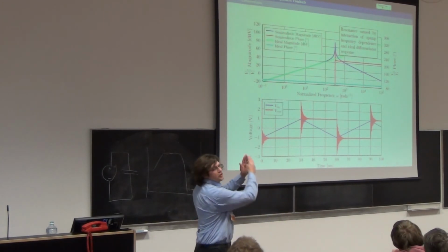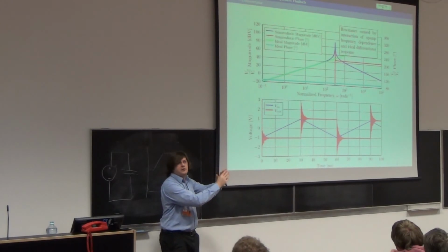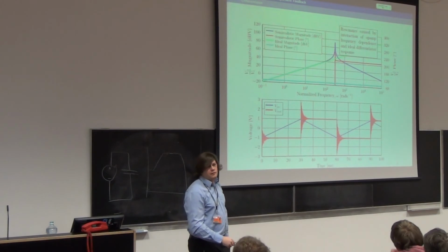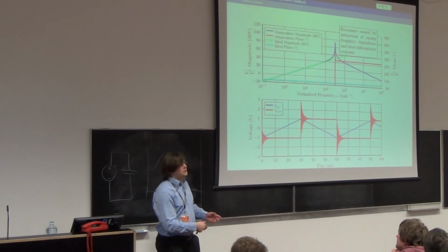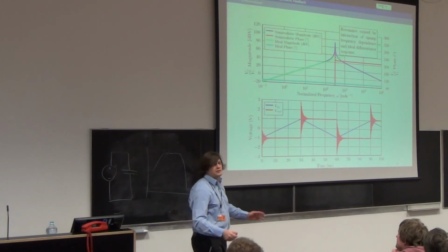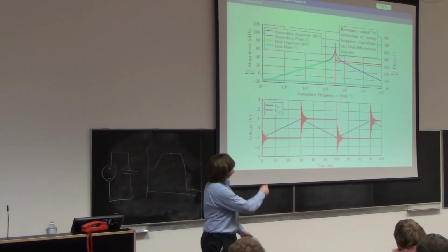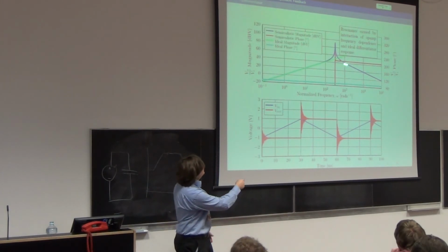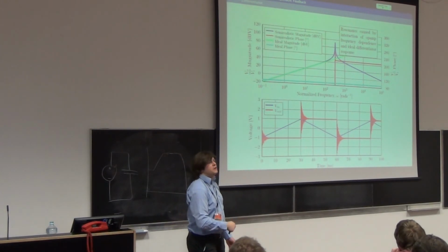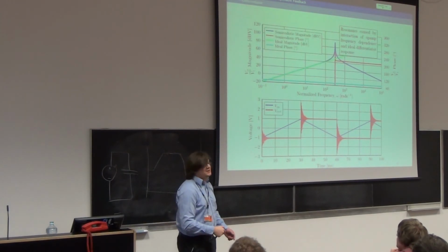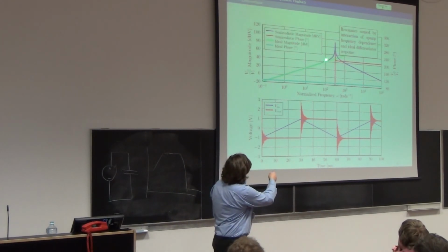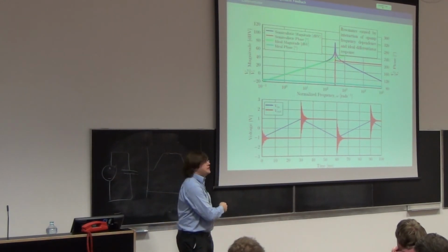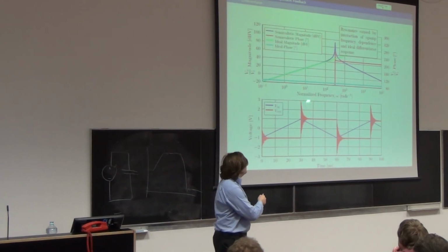If you increase the Q, it makes it sharper. Decrease the Q makes it more spread out. So you have to think about it. My comment about bandwidth and Q was separate. You can either reduce the bandwidth sufficiently so that this doesn't become a problem, but you lose all this integrator space, or, well, you can't use that anyway because it resonates, or you can decrease the Q and make this much less sharp. Anyway, you have to be careful where you use your differentiator, otherwise you'll end up with this sort of situation.